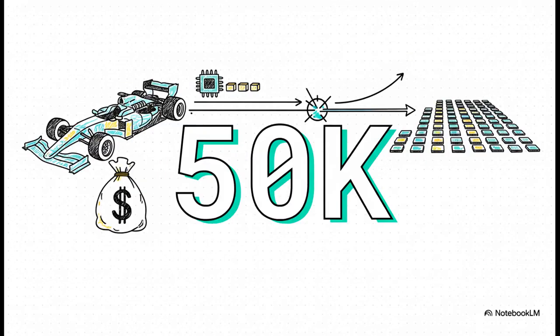So when does it actually make financial sense to build that Formula One car? Well, this number gives us a pretty good clue. ASICs have this huge upfront design cost, but each chip you make after that is cheaper. So for a product with a small production run, FPGAs are a no-brainer. But once you're planning to make tens of thousands of units, you hit this crossover point where that big investment in a custom ASIC really starts to pay for itself.